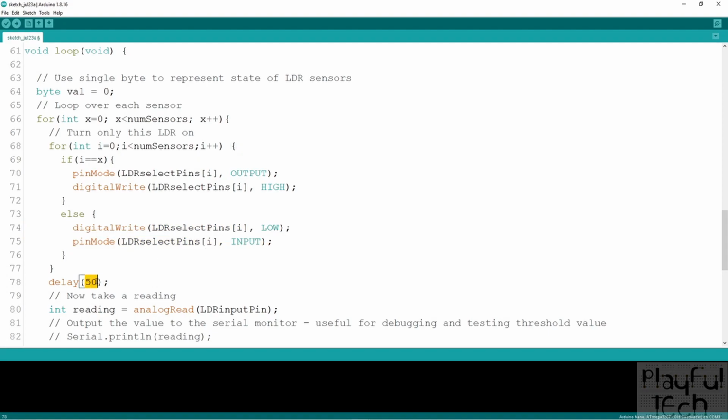We're just going to delay for 50 milliseconds after having changed those pin settings. I don't honestly know if that's actually required or not. But to me it would seem to be sensible to stabilize the circuit, because we've switched an input into an output and an output into an input, and just to wait 50 milliseconds to make sure that those have settled down before we take that sensitive analog reading at the ADC chip would seem to be wise to me.